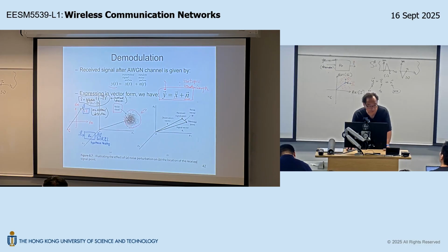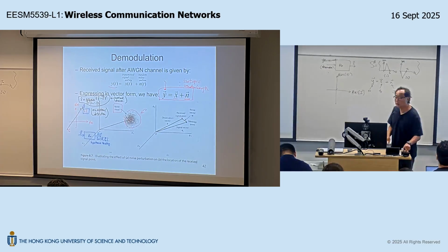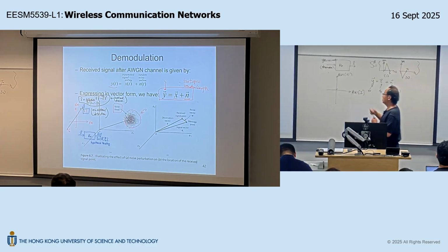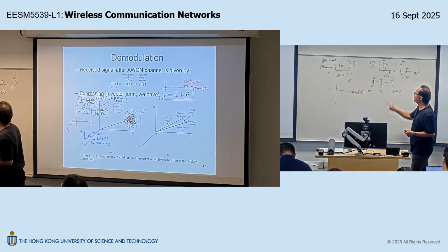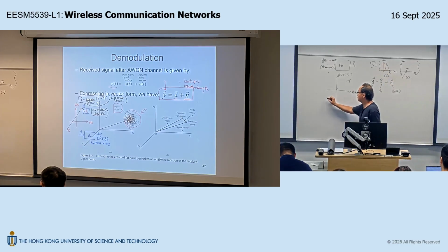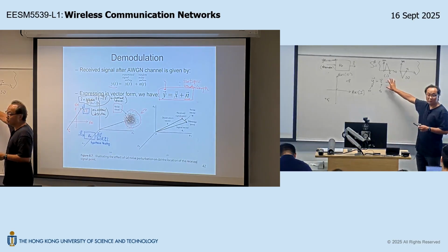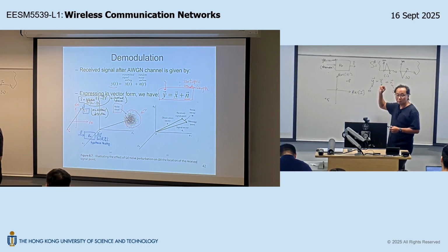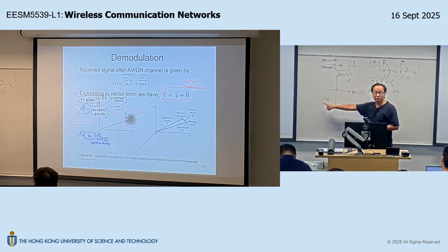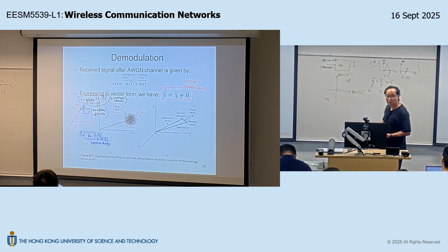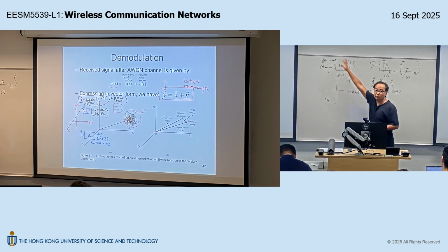So let's focus on the first goal first. How should we design this receiver? Let's say, again, for the binary modulator, this is the corresponding signal set geometric domain representation for S1(t), and then this is S2(t). Once again, if there were no noise in the channel, then the received observation could either be this or this, no other places. But because of the presence of noise, the receive point can be anywhere in the space.